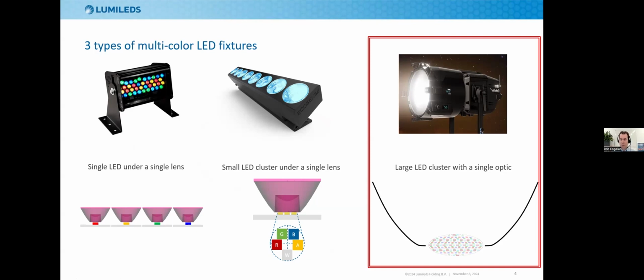Around this LED array is then, I sketch schematically here a reflector, but it can also be a more complex optic like above, where you can still do some zoom, change the beam diameter and such. But in essence it is this. So why is this a big thermal headache? Because all the energy is concentrated in this 20 or 30 millimeter array, and you need to dissipate that heat in order to keep the array cool, or at least not overheating.